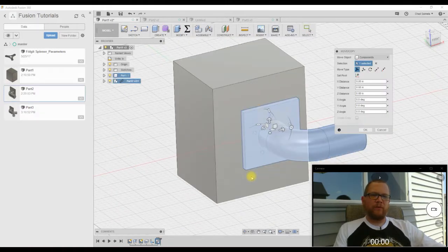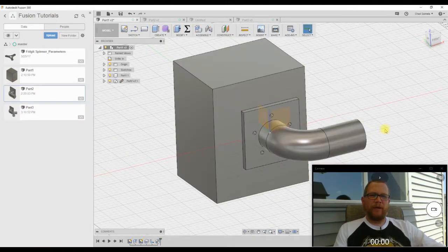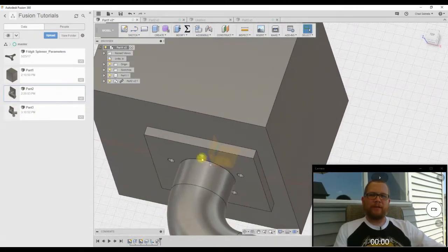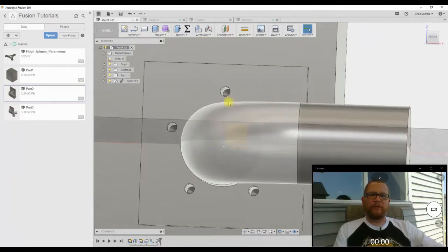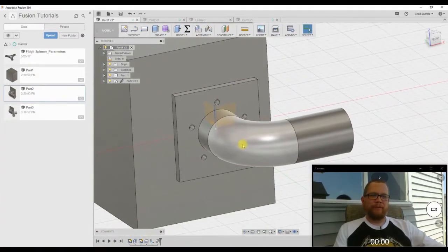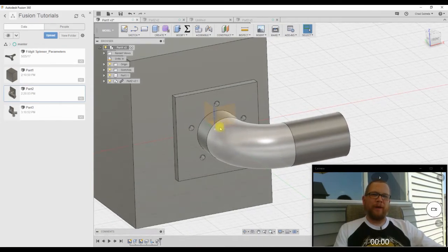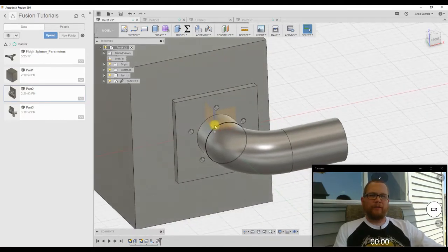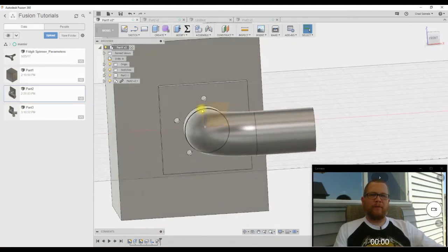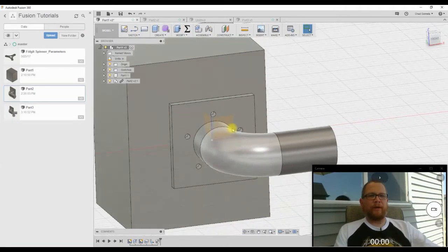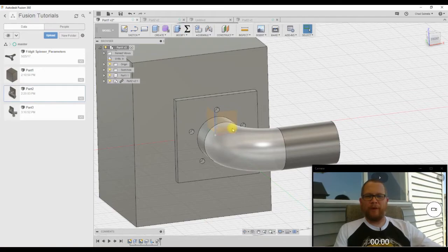And it takes a second. So what it does, and I'm just going to hit OK, is it brings that part in and locks it right into the origin points. Because I built my little bolt-on piece with the origins set up around the mounting pattern, just like the main block, it drops right into that spot, and now we've got our part locked right down in place, right on top of that bolt hole pattern.